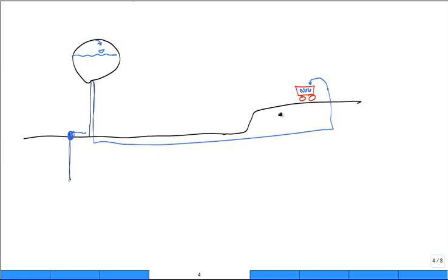So it's not potable. You ever seen that sign? Look around. So anyway, if they would have stuck it all the way in, and then all of a sudden there was a break in the line, what would have happened because of the elevation difference? It would have sucked that right out of that tank and all the way back into the line somewhere, and would have contaminated your water supply.